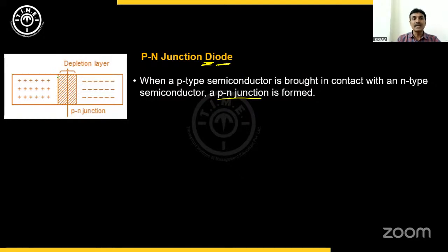Simply, this region is depleted of mobile charges. The charges or ions in this region are immobile. To the left of it is the P-type material, and on the right side the N-type material. To the left of this depleted region, we have free holes. These holes can move. And to the right of this, there are electrons which can move.